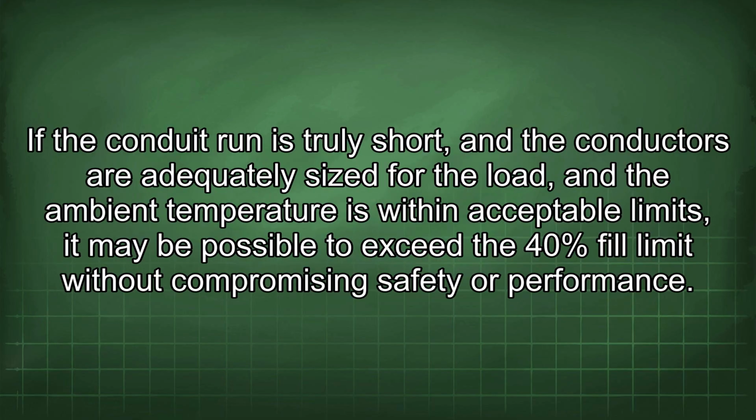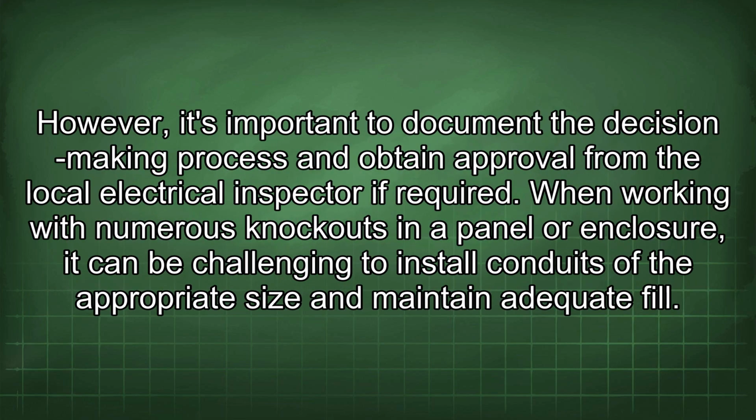If the conduit run is truly short, and the conductors are adequately sized for the load, and the ambient temperature is within acceptable limits, it may be possible to exceed the 40% fill limit without compromising safety or performance. However, it's important to document the decision-making process and obtain approval from the local electrical inspector if required.